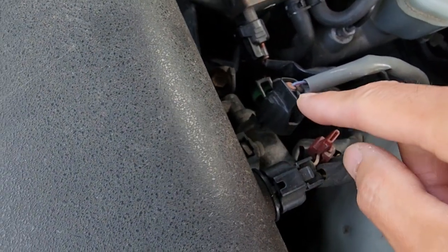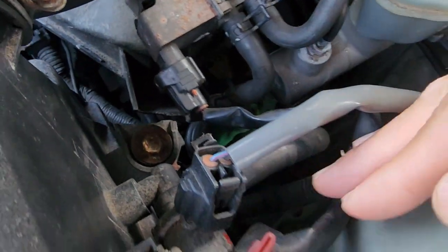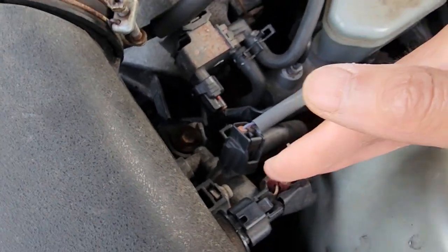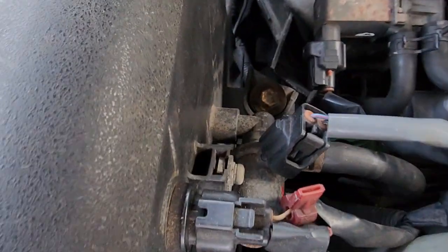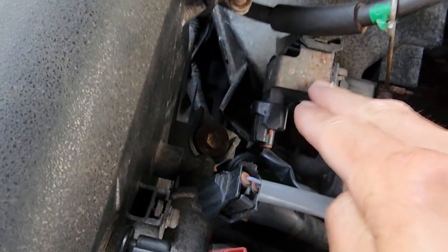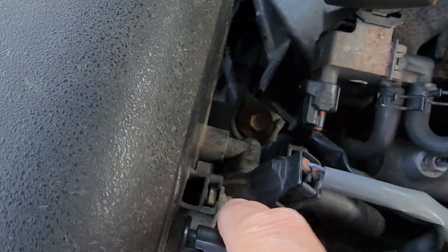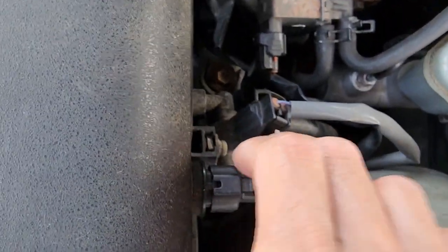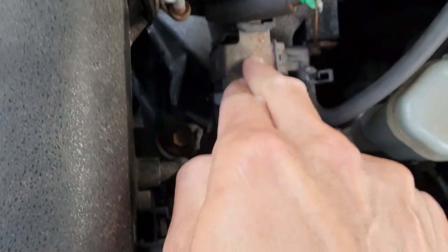working properly by applying the voltage here, and make sure there is no crack in this line hose, or the metal line that all the way goes to the canister. This is VSV for EVAP, and this is VCC for this breathing mode. This fail very rarely happens. Mostly this causes the problem.